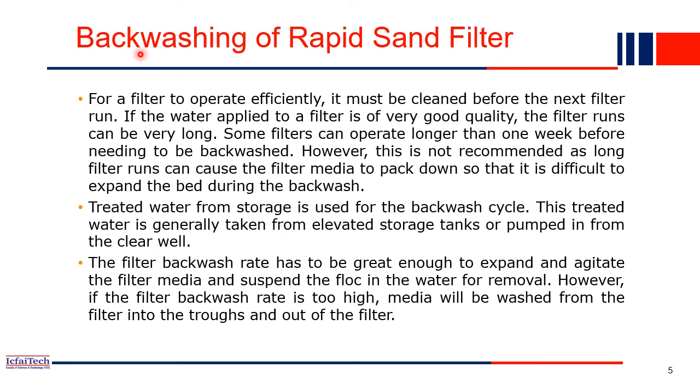Backwashing is done on a weekly basis, or maybe even daily, depending on our requirements. For a filter to operate efficiently, it must be cleaned before the next filter run, right? If the water applied to a filter is of very good quality, then the filter runs can be long. If the water quality is very good, maybe you can clean it once a week. Some filters can operate even more than one week. After one week you need to do backwashing, right? However, this is not recommended, as long filter runs can cause the filter media to pack down, so that it is difficult to expand the bed during backwashing. That is why it is better to clean frequently, maybe daily once, or daily for half an hour, for the backwashing of the filter medium.